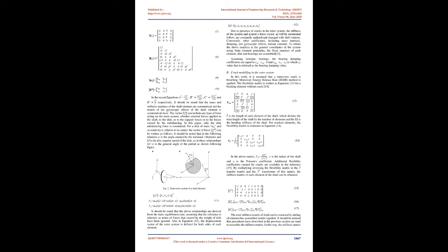Guo et al., 2017, set up an experiment to study the dynamic response of a rotor with a breathing crack as it passed through its 1/2, 1/3, 1/4 and 1/5 subcritical speeds. The vibration signals of the test bed during the coasting up process were collected. Whirl orbit evolution at these subcritical speed zones was analyzed.